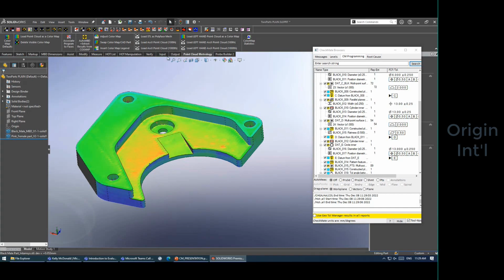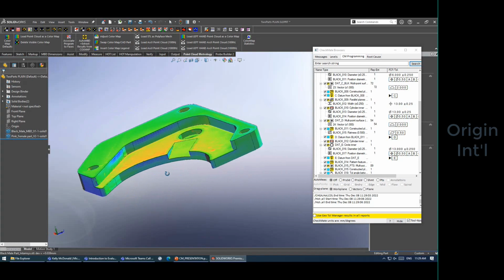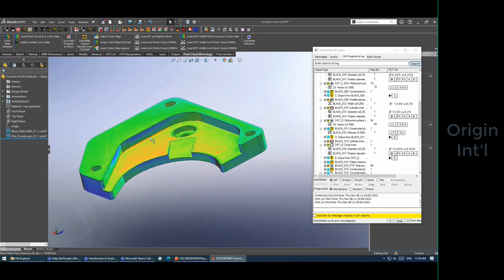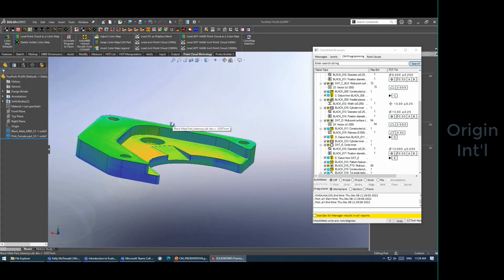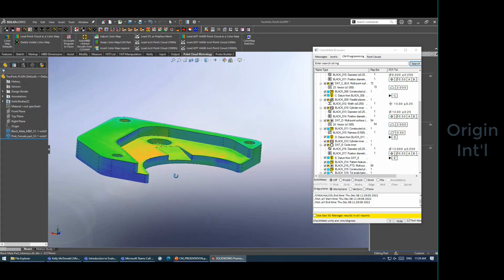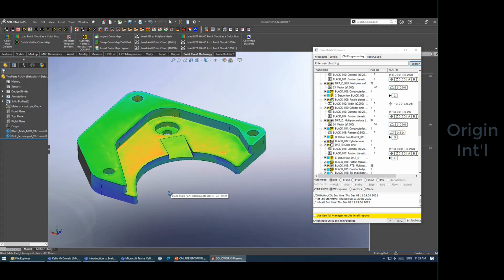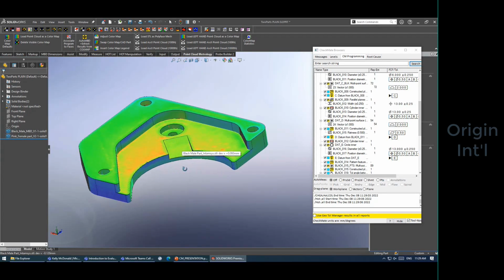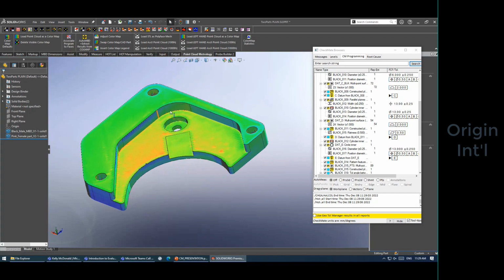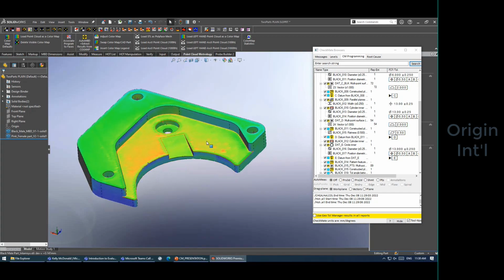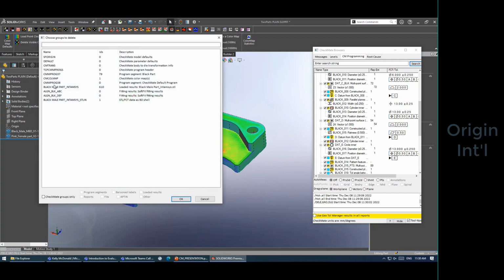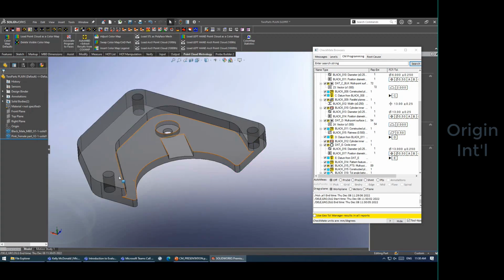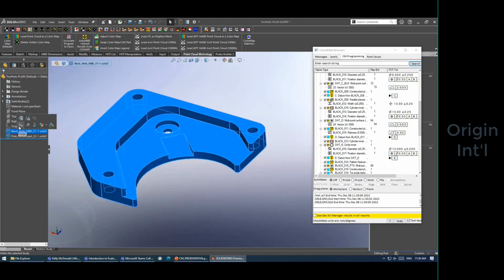So I don't need the color map for the blue part anymore. We can see that blue is telling us it's a little bit shallow, meaning there's not as much material as there should be. So by the color map, it's already a little bit undersized, but in these areas that's probably a good thing. I actually don't need that color map, so I'm going to delete it because we're going to have a second one on the other part. So let's just go do our SolidWorks magic.